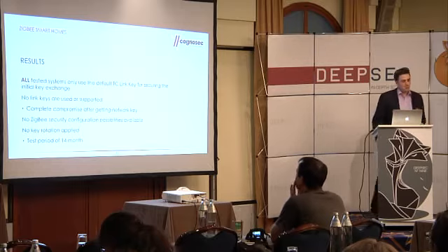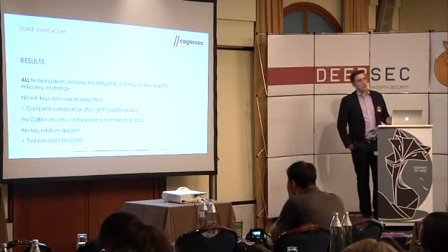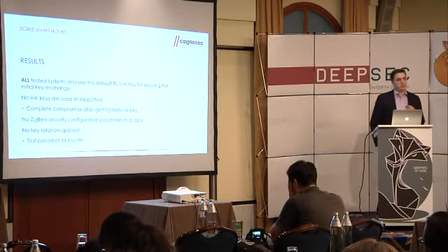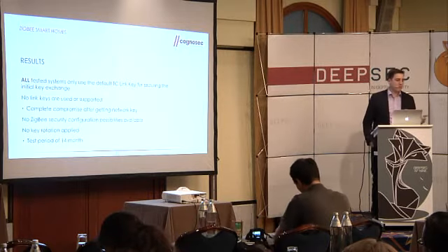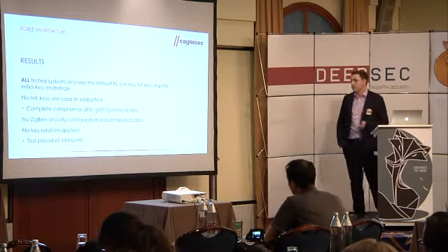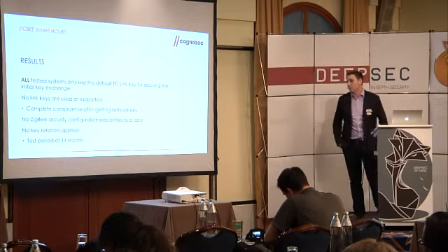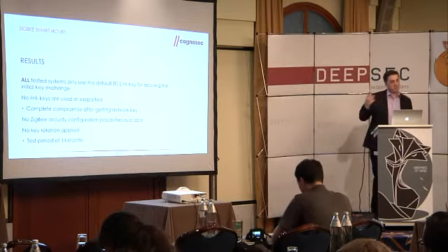There are no ZigBee security configuration possibilities. This means I can't change the network key. This means if it's compromised, you have to throw the devices away, because there is also no key rotation applied. We tested over a period of 14 months now. There is no key rotation.